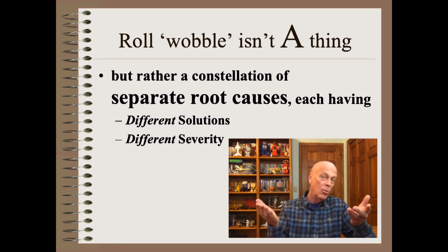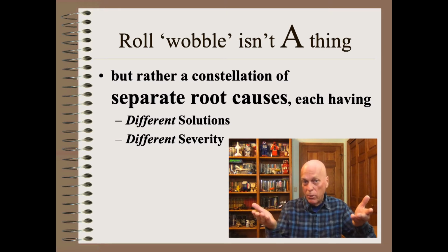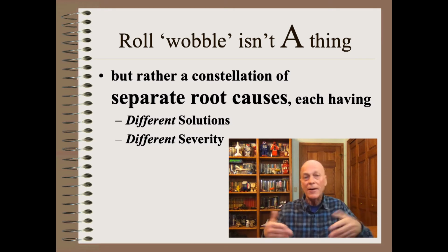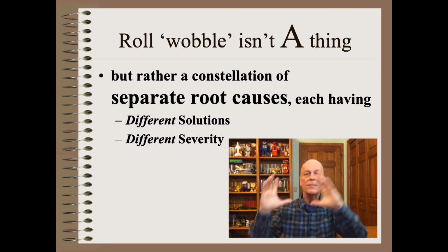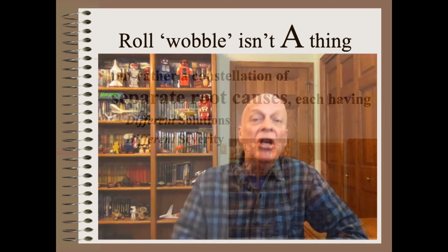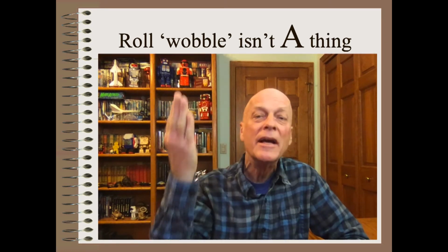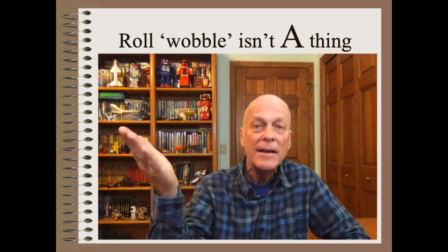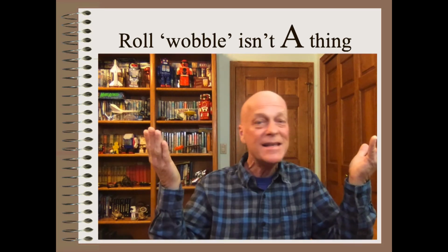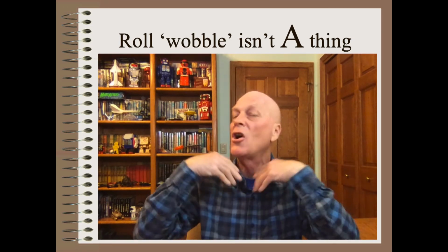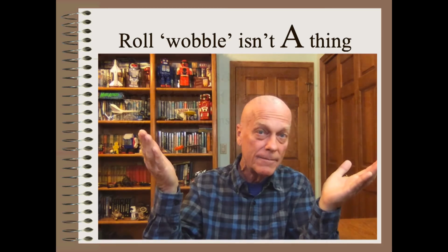People who followed my work will easily appreciate this approach. That is, a wrinkle is not a wrinkle is not a wrinkle. There are about 20 different causes. The same with roll wobble, rough roll edges, telescopes, core crush, and many other defects. You absolutely must get the correct subcase in order to get the correct remedy list. It is easy, as you've seen in my prior teachings with other defects. It is also easy with roll wobble.